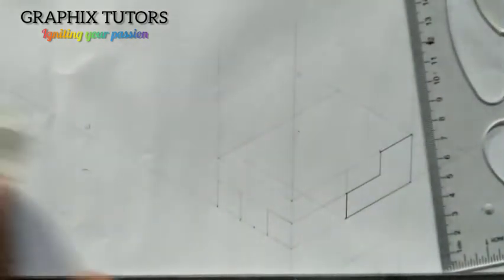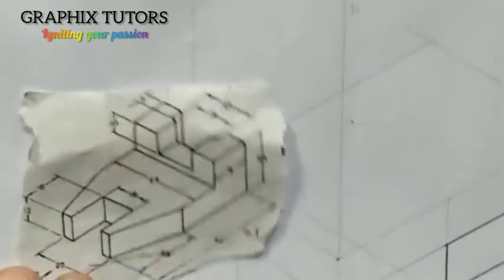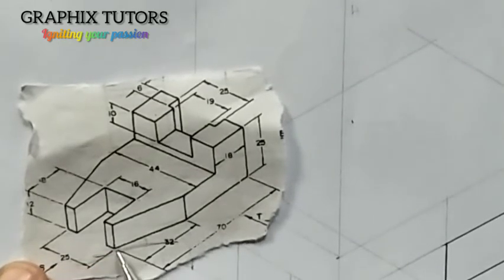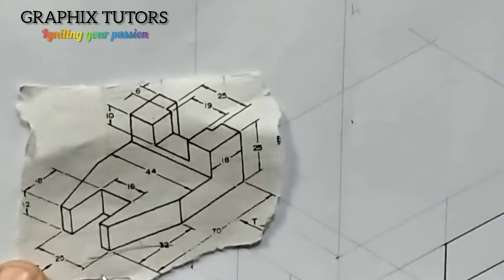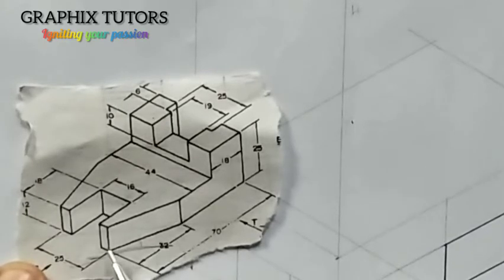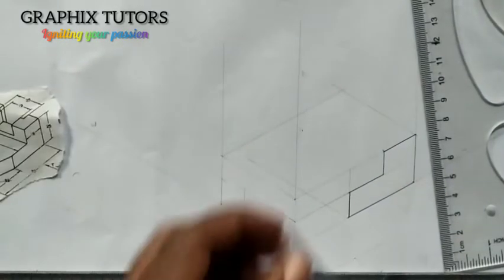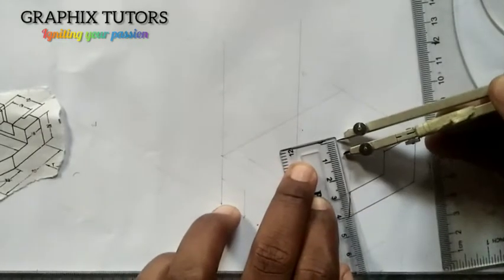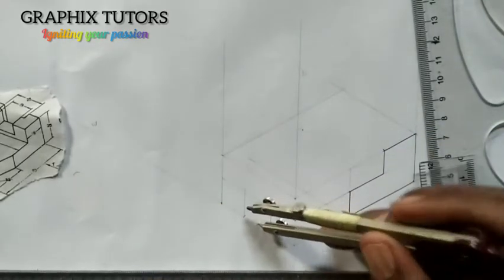Now after doing that, if you look at this very well, you will discover that there's a thickness here. So from that same center that you have here, you still measure 12.5 to the left and also 12.5 to the right to get 25, right? So let's do that. So if I take my meter rule, I'll measure from 0 to 12.5 here, right? And I'll place it at the center here. I'll mark left